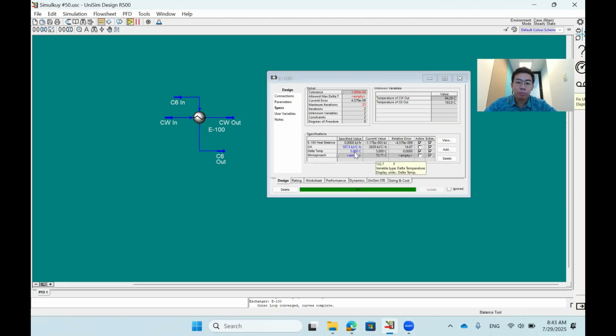The best practice for approach is above 5, around maybe 10 up to 20. So, for example, I want to make it 20. Then I change this 5 to 20. Okay, it will show the FT correction factor is low, but no problem. What I want to show you is what the approach is. So now I will shift T to see the temperature.